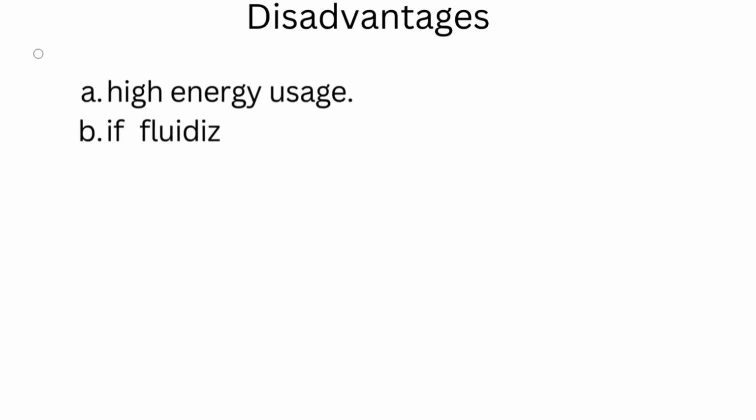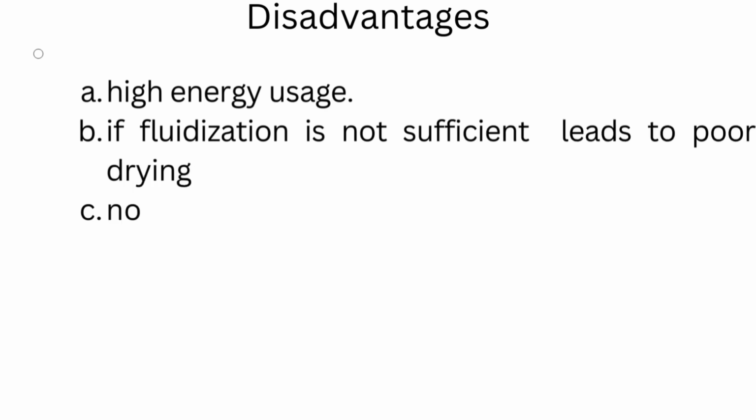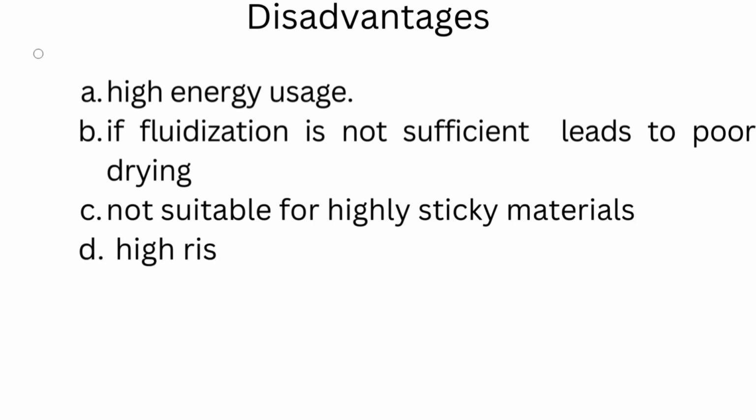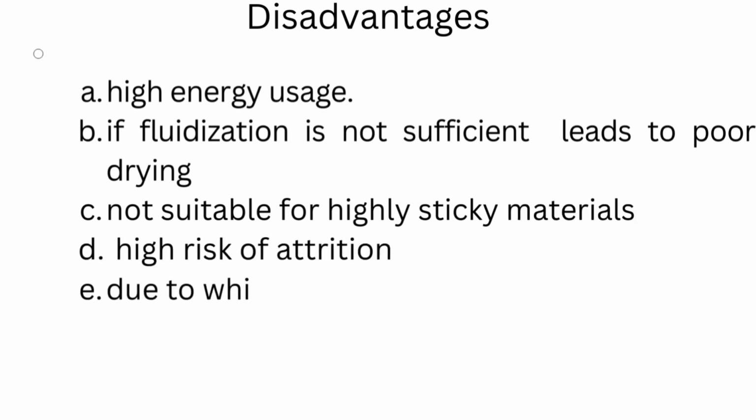Disadvantages of the fluidized bed dryer: high energy usage. If fluidization is not sufficient, it leads to poor drying. It is not suitable for highly sticky materials. There is a high risk of attrition, due to which there is a greater chance of particle size reduction.